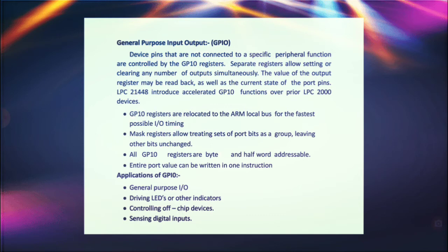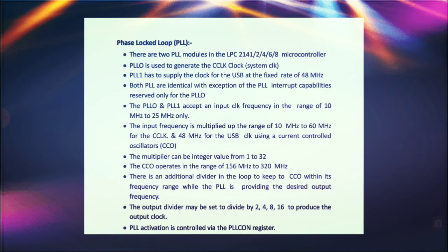LPC 2148 introduced accelerated GPIO functions. GPIO registers relocated to ARM local bus for the fastest possible I/O timing. Masking registers allow treating sets of port bits as a group, leaving other bits unchanged. Applications of GPIO: general purpose I/O, driving LEDs or other indicators, controlling off-chip devices, sensing digital inputs.